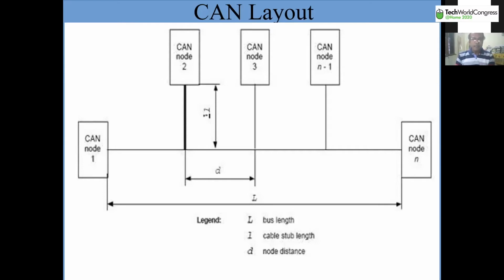And just imagine if you had used so many sensors with so many wires and so many supplies, because every sensor needs to have a supply voltage and every sensor needs to have a signal wire, either one wire or two wire or four wires. So for 70 sensors and so many wires, if you had used, the weight of that motor vehicle would have risen by 50 to 100 kgs.